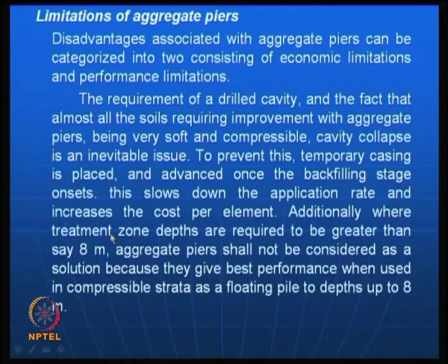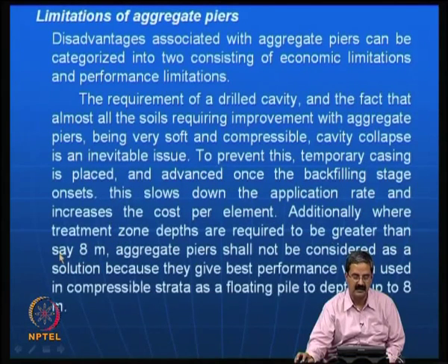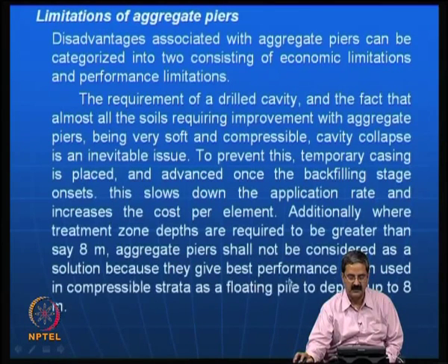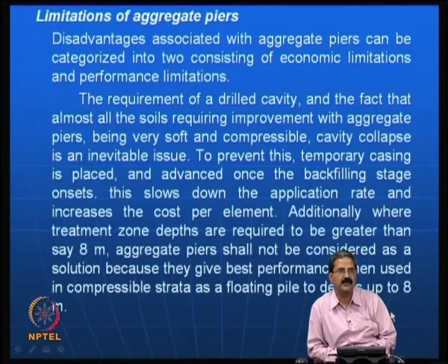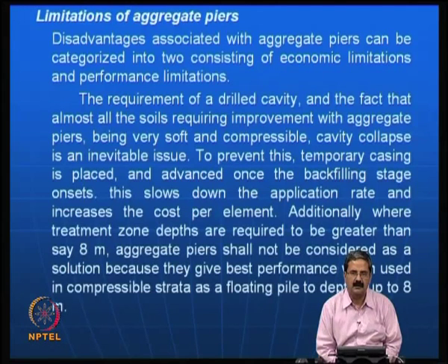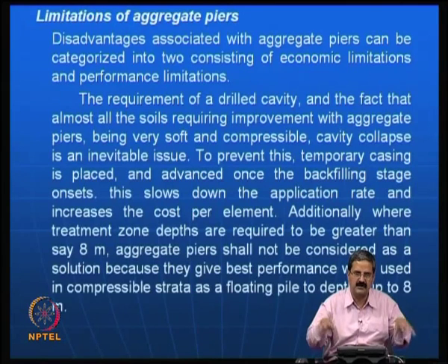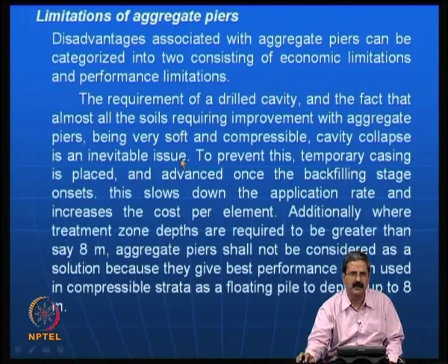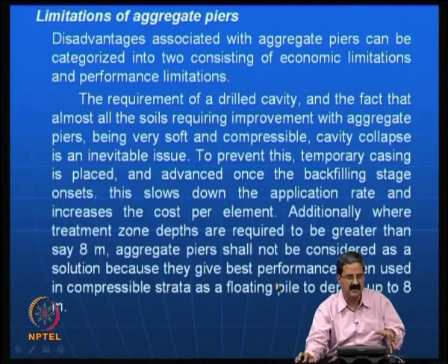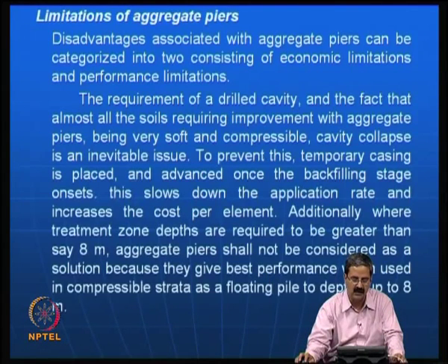Additionally, where the treatment zone depths are required to be greater than 8 meters, aggregate piers shall not be considered as a solution, because they give best performance when used in compressible strata as a floating pile to depths up to 8 meters. So these are all more like floating piles or a simple soil reinforcement system, which is quite effective. In fact, people have been using some of these things without much soil mechanics, because intuitively they feel that if you do like this, definitely there will be an improvement in bearing capacity. That is how people have been able to work it out.